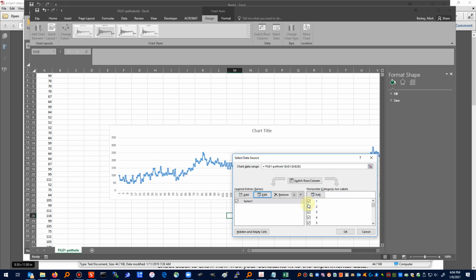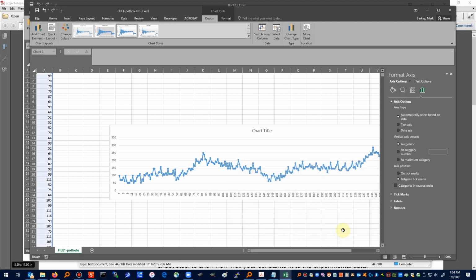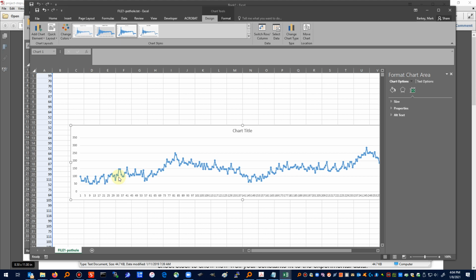We'll look at a couple hundred data points so we can see what's going on here. Now, computer data acquisition systems bin your data set. So it takes voltages and converts it into a number, and sometimes that number is in one level, one zone, sometimes it's in another zone, sometimes it repeats and stays in the same zone. So like here's a bunch of instances where we have the same number. So it looks like the value is 111 microstrain a few times.